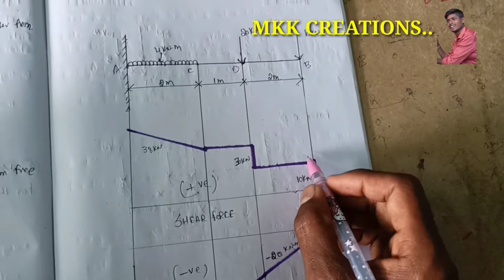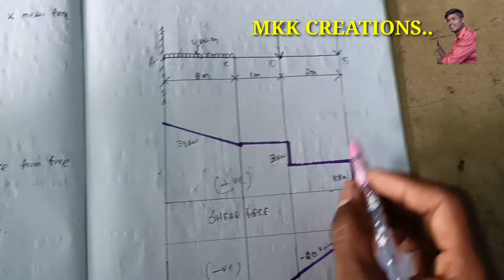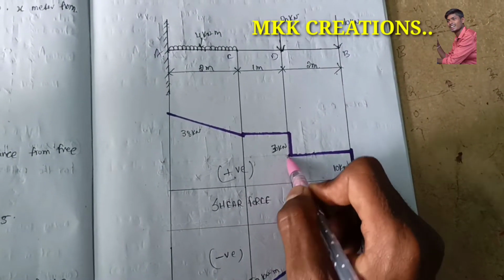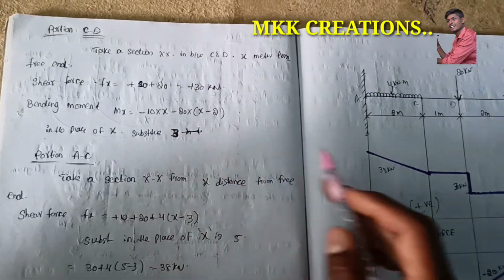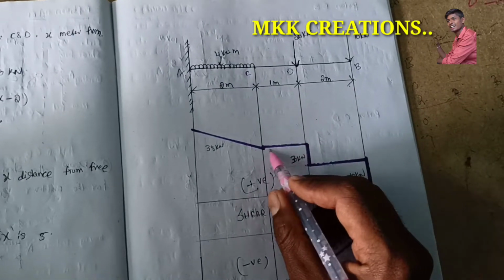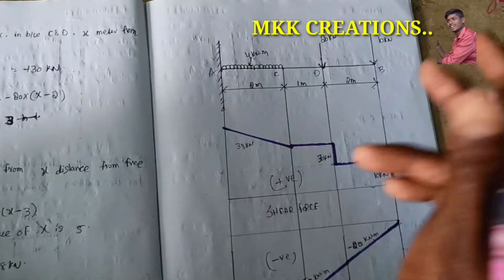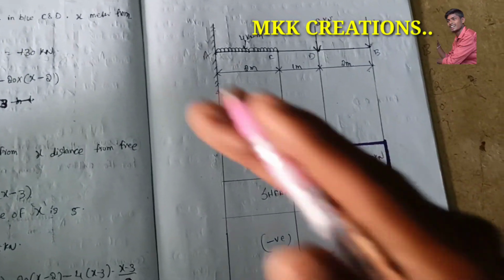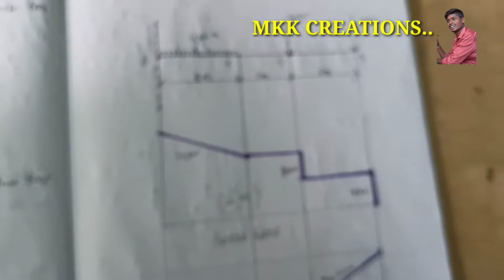Then there is no load acting in between BD, so we draw a constant line. Again at point D we have 30 kilonewtons, plus 30, and in between there is no load, so a constant value. And again wherever we get a uniformly distributed load, at that time we draw an inclined line.